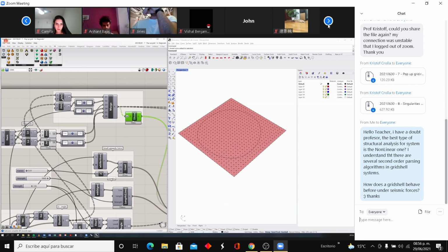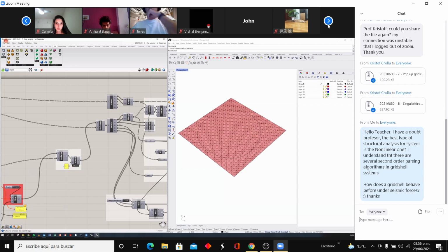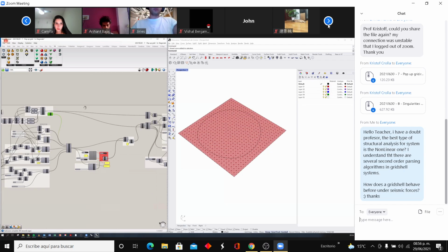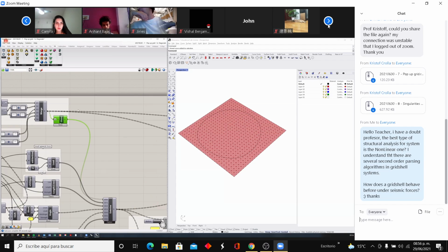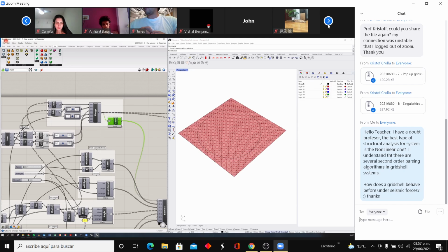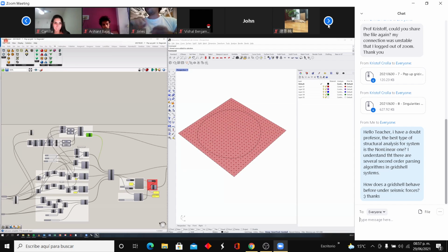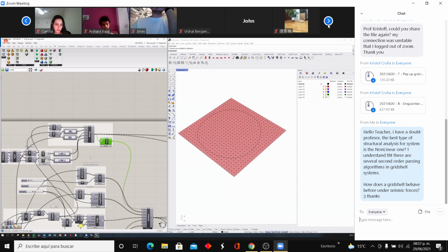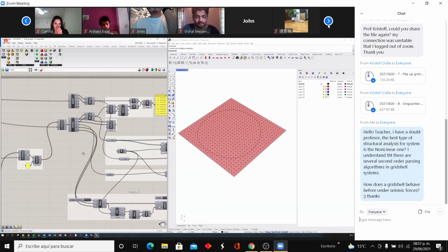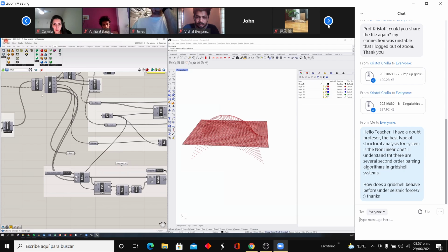Then at the other end of the calculation, after you unflatten it, it keeps the data structure intact that you have put in at the beginning. So branch 0 and branch 1 will be my main members, UV, branch 2 will be my mesh, and branch 3 and 4 are the diagonals that I'm working with. So after my calculation, let me just show this. After the calculation, I get my curves in the U direction. Let me switch that all off there.